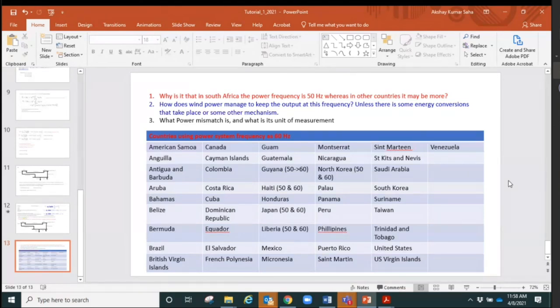So there are limits: stator winding current, MVA capacity, reactive power capacity, power factor, stator current capacity, rotor current capacity, and all those you consider. It's not only one parameter, one is related to the other, and they are always reflected in each other.